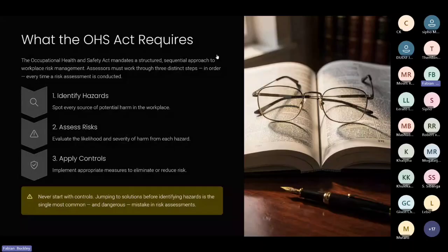Now, the best way for us to conduct a method statement as HSE professionals is that we need to sit around the table together with the construction manager and the supervisor executing the work. Also, sometimes the artisans that are performing the activities. So you create a committee of sorts, with engineering where engineering is required, and also quality control. It's very important that we also have them as part of the process.